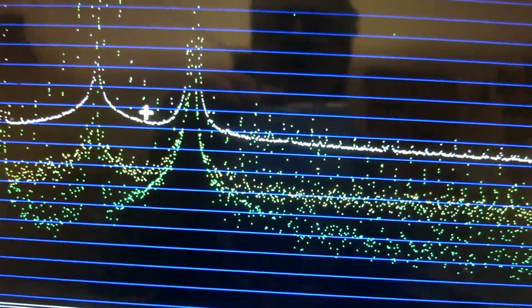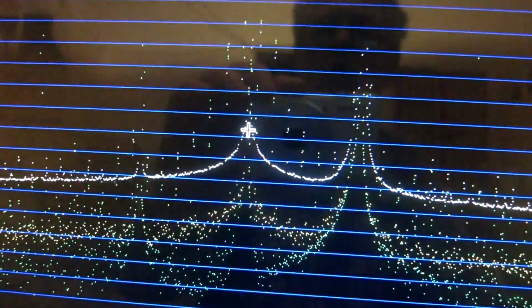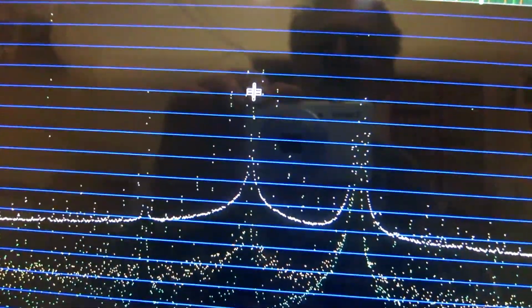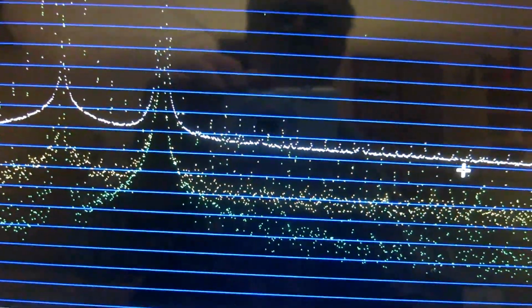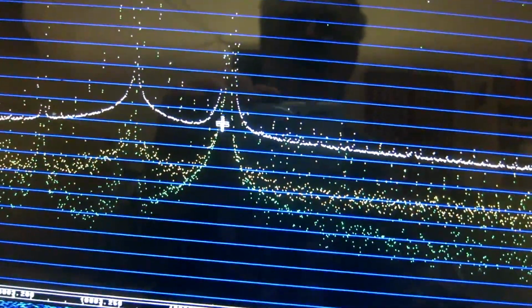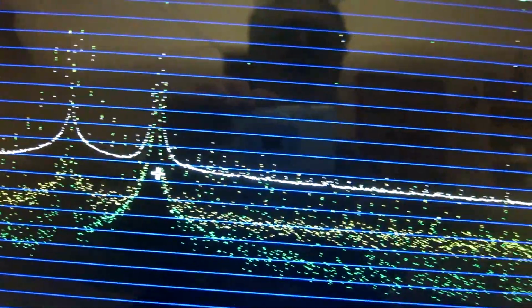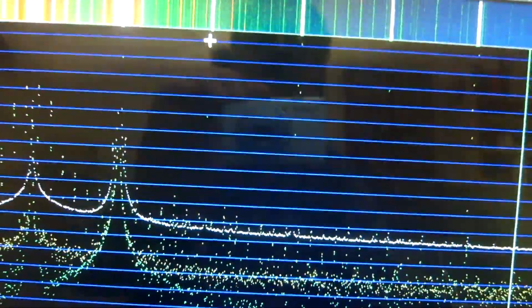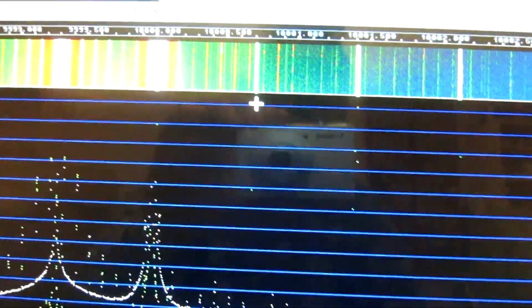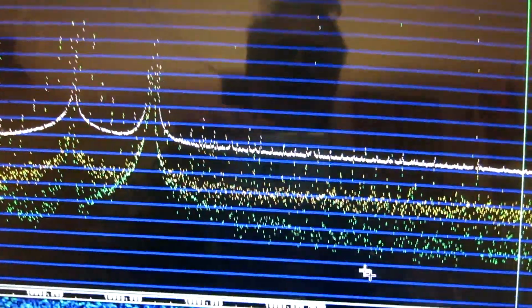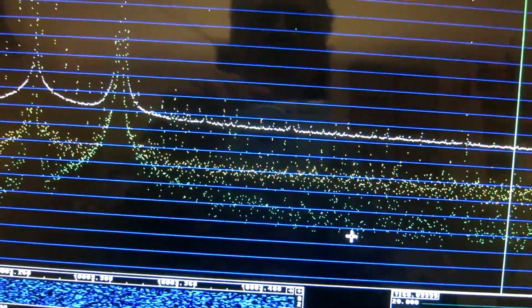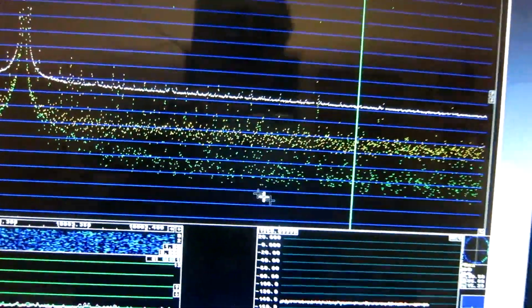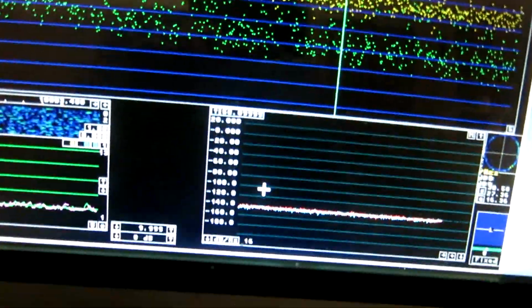There is every 50th Hertz from the audio. This is DC, and then there is 50 Hertz, 150, 250, all the odd overtones. And then there are modulation sidebands, 50 Hertz on each side of the strong signal. And then there are modulation sidebands on the overtones produced by the nonlinearities of the mixers. And those give some structure to the correlation spectrum. Anyway, I will save this information.